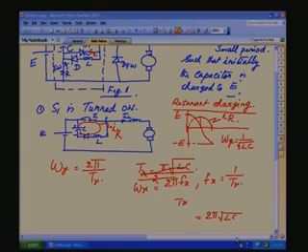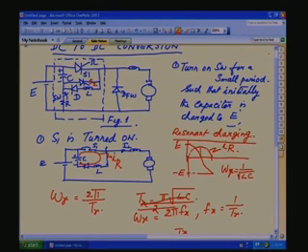Now, this is very important. So, this much period we require for the capacitor resonant charging. Once the capacitor is charged in the opposite direction, then only it will be ready for commutating the main thyristor S1, this S1. Now, this resonant period should be as small as possible. How small, we will come to later when designing L and C. So, assuming the capacitor is charged, now it is ready for commutation.